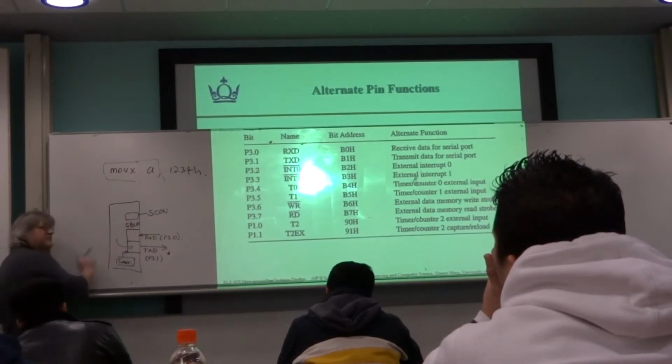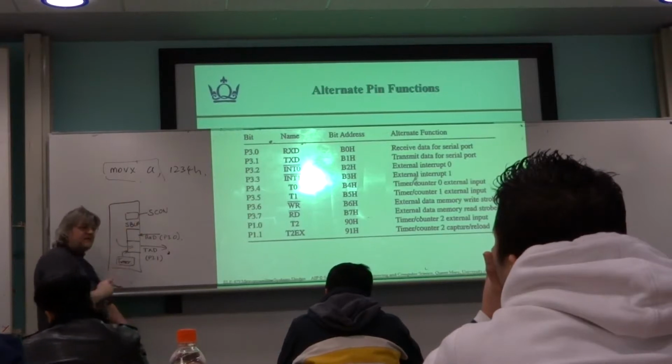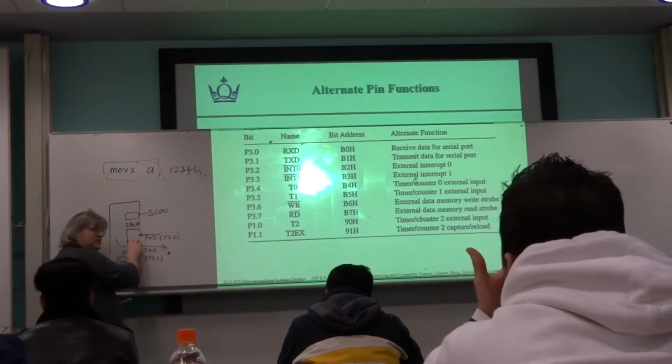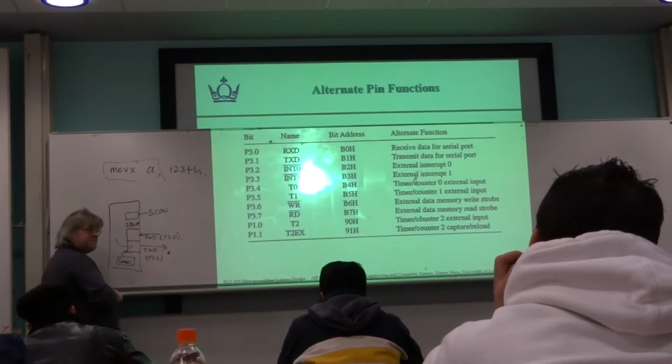So if you've got 8 bits of information to send out, like a character, you just write your 8 bits into this buffer and then you can go and do something else. You can make a cup of coffee, go watch some telly, do whatever you like. This will automatically be sending out those 8 bits at exactly the right speed.